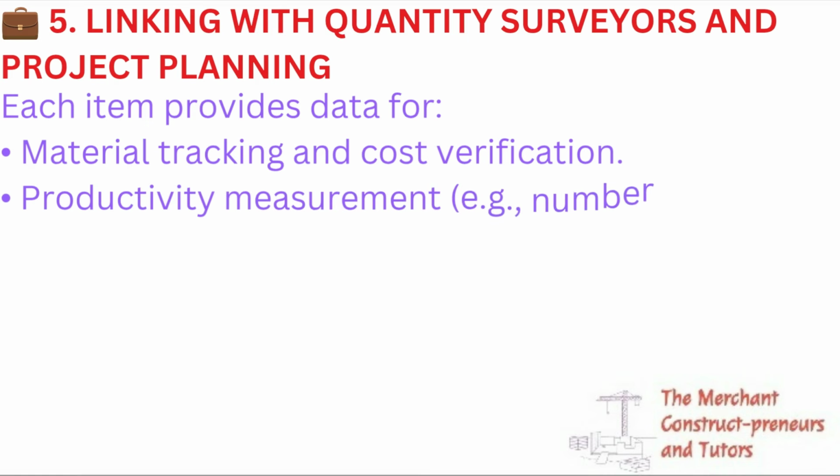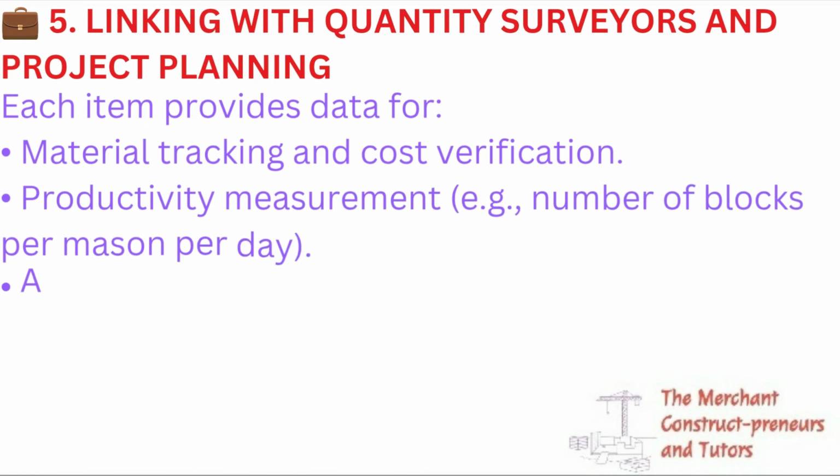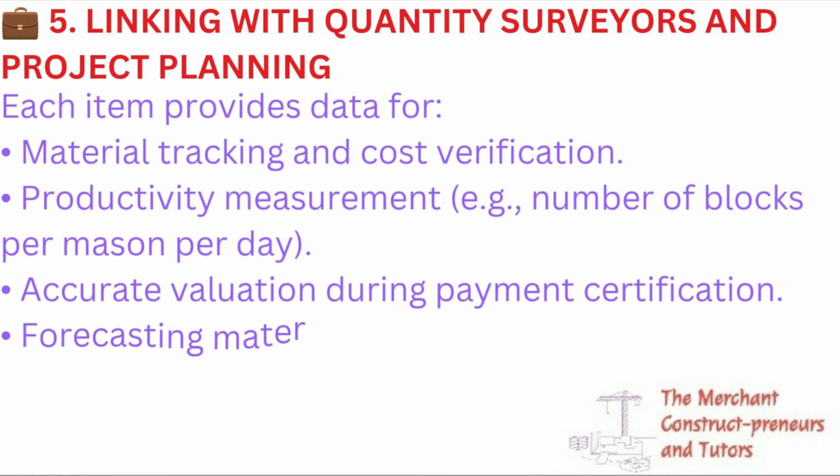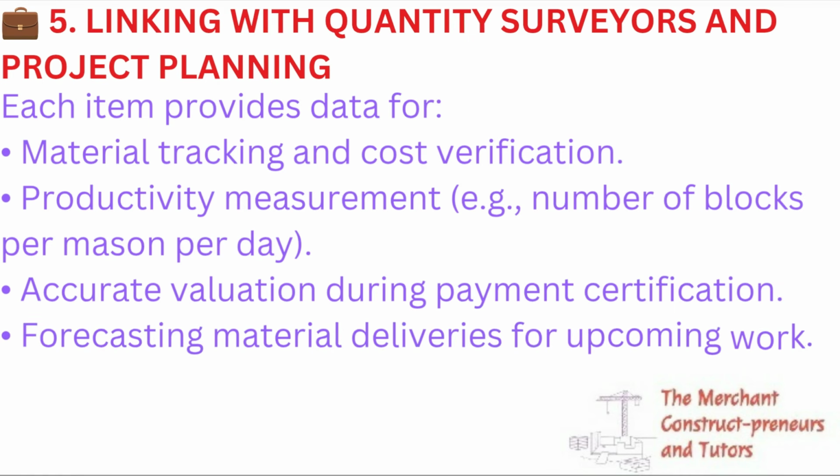So the next thing is we need to link with the quantity surveyor and project planning manager. So after doing these things, you are not doing your work in isolation. The quantity surveyor needs to be aware. The project planner also needs to be aware. So of these items, you provide data for them. The material tracking and cost, just as I said, the documentation, productivity measure, how many blocks, how many masons are doing a particular block, so that we know if there is progress in the work, or we are using more people for lesser work.